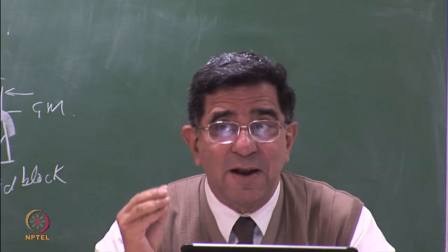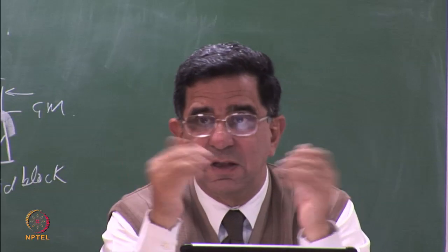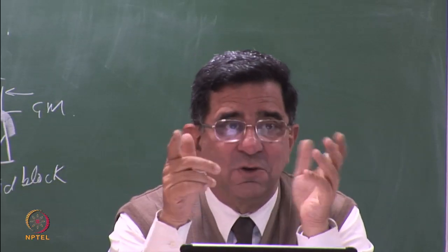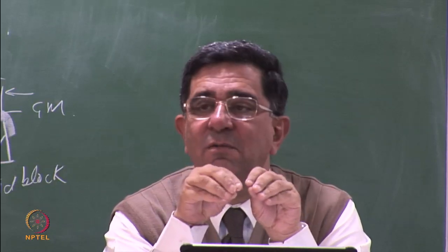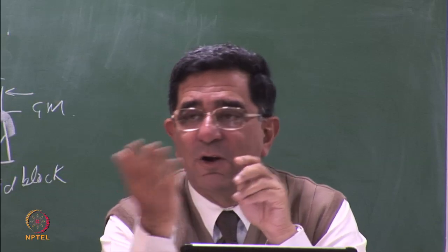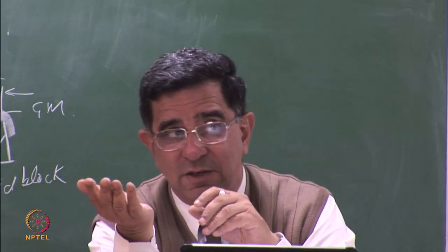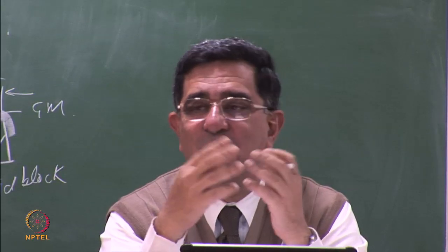Some of the bentonite can actually extrude out of the geotextile. Why? Because the geotextile at the top and the bottom is not a geomembrane. It has a finite pore space. So the water is given to the powder inside that. On the top and at the bottom is the geotextile. The bentonite swells and it comes out of the pores.